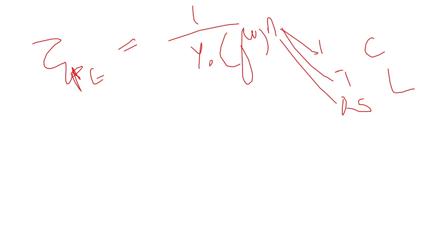So you should know what an interstitial movement is. It can be the movement of the interstitial, so if a cation is diffusing from one point A to another point B, it can happen in multiple steps or in a single step. If in that movement a vacancy is left, in some cases we feel like the vacancy is getting shifted. There we say it's because of vacancy shifting, vacancy diffusion.